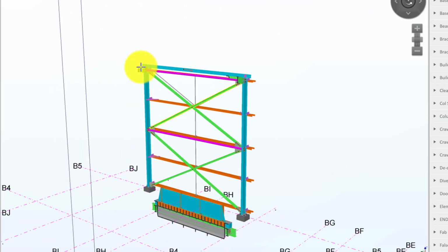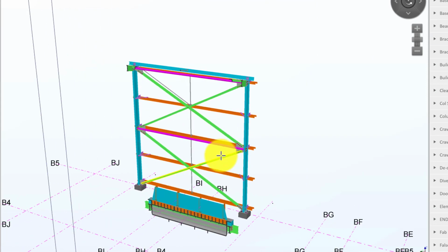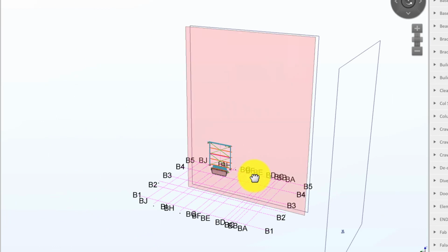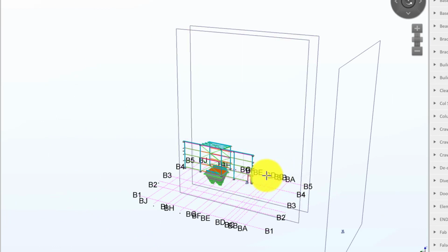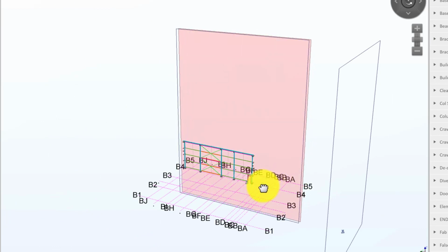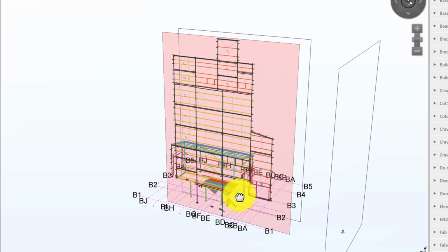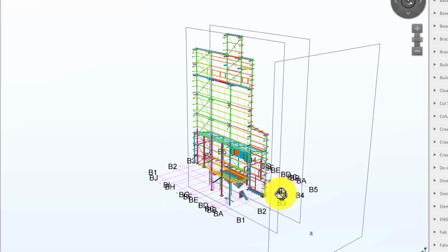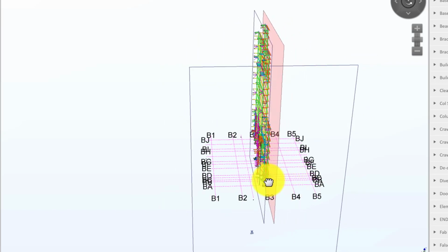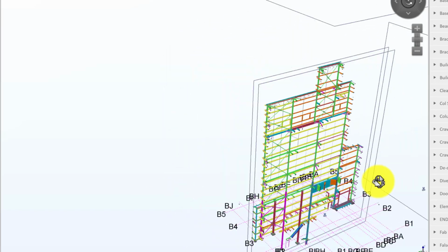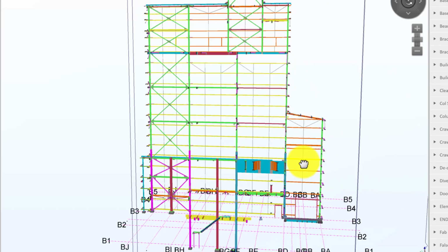Here you can see very traditional cross bracing, horizontal pipe for compression load, and that kept that first bay stable. And then we go to another smaller bay, and then once again traditional cross bracing layout. Then we get to the main building, and here you will see a large braced bay on the structure all the way up the left hand side.